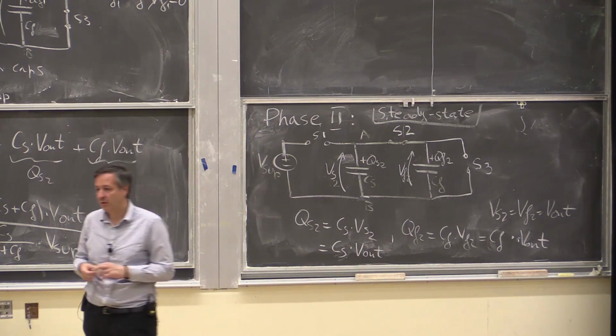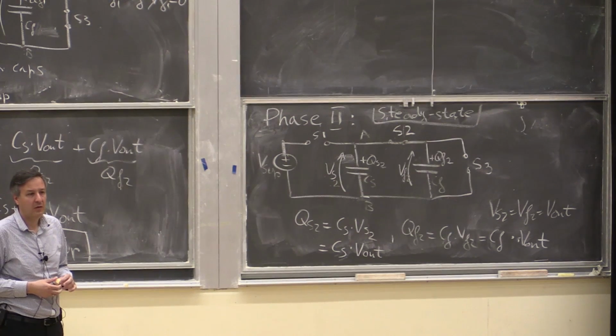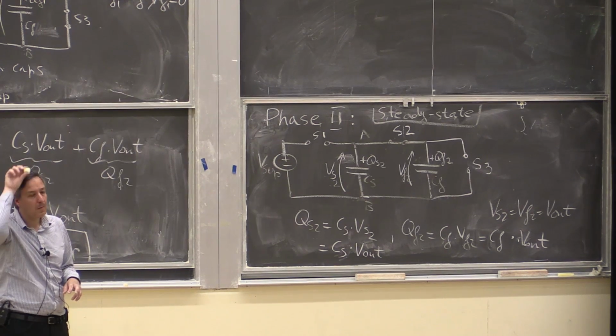Okay, yes? Is the circuit the same whether you touch or not? The question is whether the circuit is the same whether we touched or not. When we did the equivalent capacitor early on, we just saw that the value of that CS changes, but if there's no touch, there's still the basic capacitance between E1 and E2. If there is a touch, you just add more capacitance. But overall, that whole thing is just one equivalent capacitor that changes value.